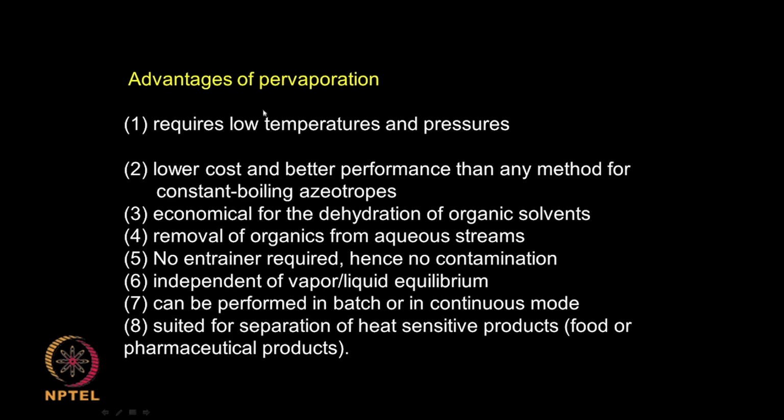So, what are the advantages? It requires low temperature and pressure. So, if there are any thermally labile products like fruit juices or syrups, sugar solutions, then it is easy to operate. It is lower cost and has better performance than, say, azeotropic distillation. It is economical for dehydrating organic solvents.